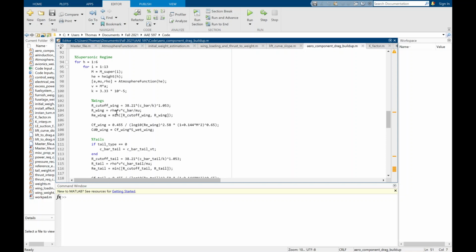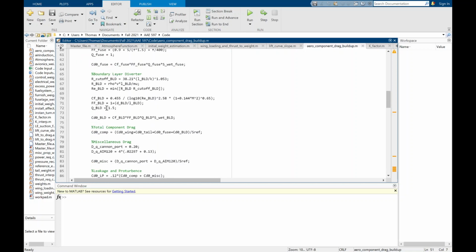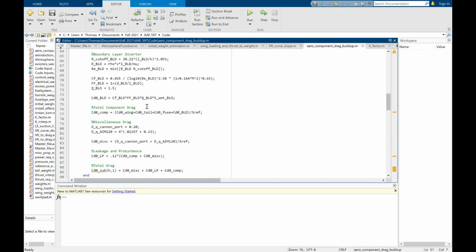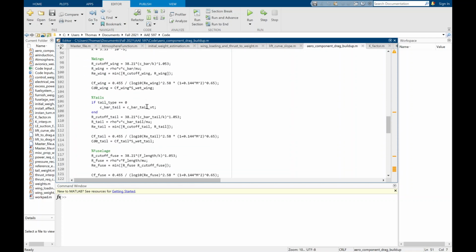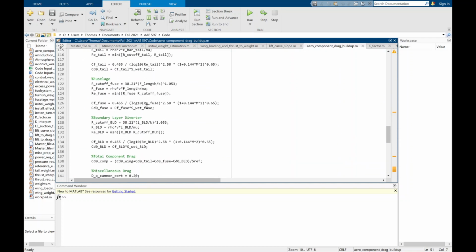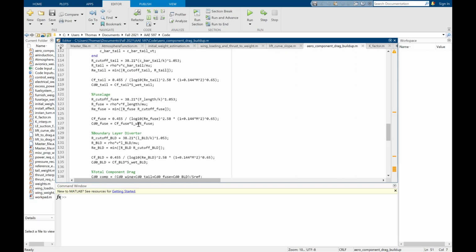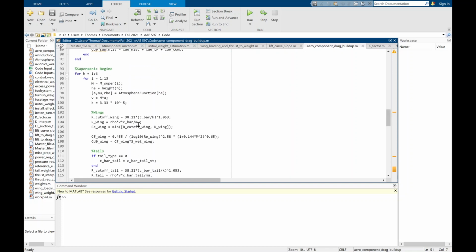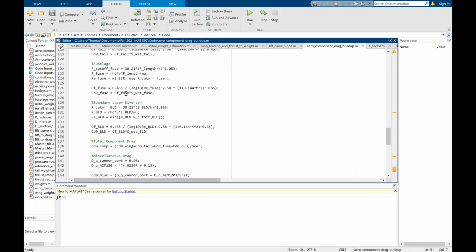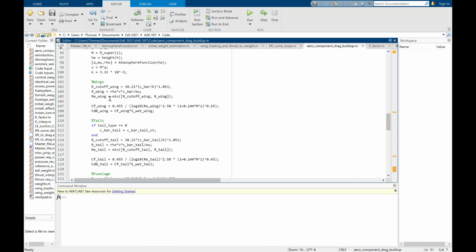Moving forward for the supersonic regime, we do something similar, but instead of having the form factor, that FF function which calculates the pressure drag due to separation, what we will end up calculating is the wave drag, which is going to be the drag due to the pressure differences across oblique and normal shocks in the flow. That's a little bit harder to estimate, I think. So these are all standard: Reynolds number, form function, and then the wetted area.